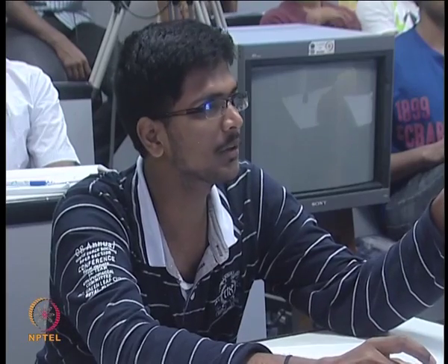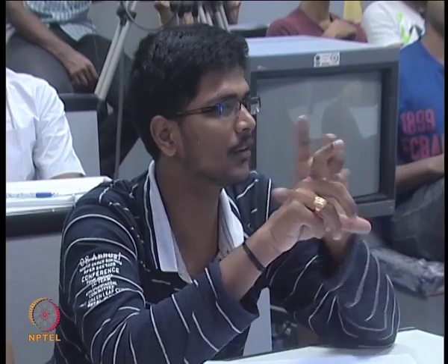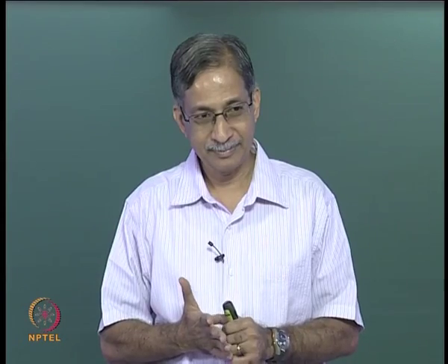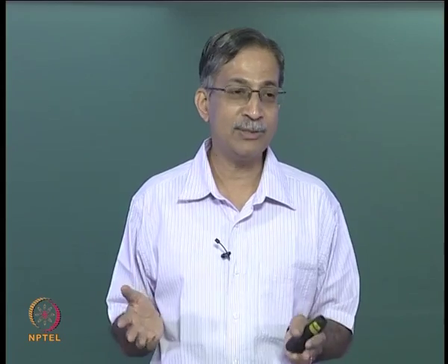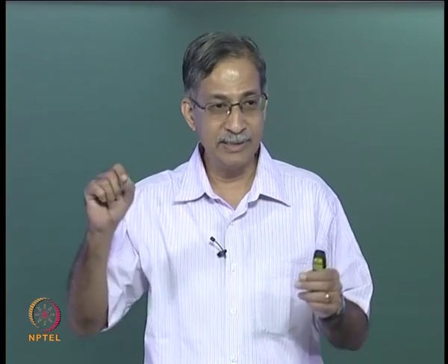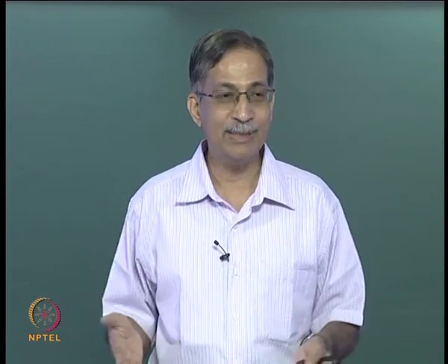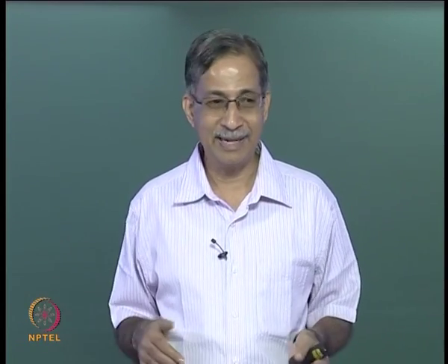So the member must be in tension, right? Tension or compression, now it will still be in tension. If the member is inclined, can you apply a horizontal reaction? You can have a horizontal reaction. You understand? So there is always an answer to any question. It should make sense. Of course, one answer is the horizontal reaction is 0, but you know that is not going to happen because it is a rigid system, it is statically indeterminate, there have to be internal forces, there have to be support reactions, but the reactions will cancel out. Is it clear? Good question.